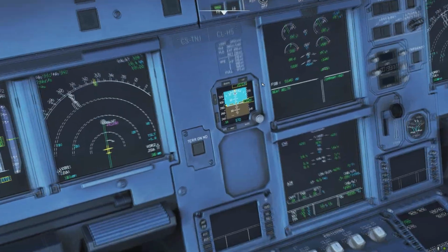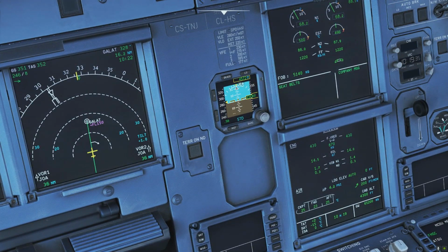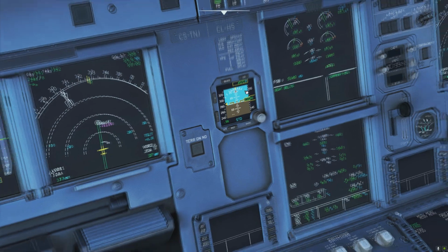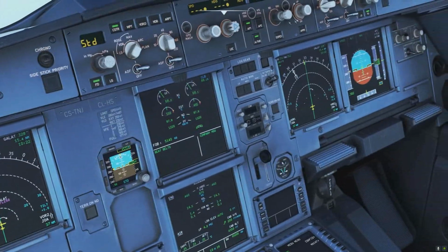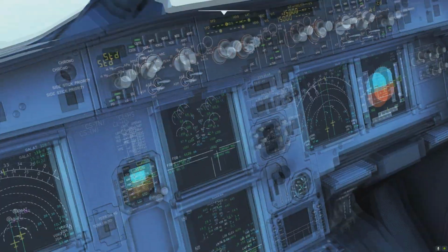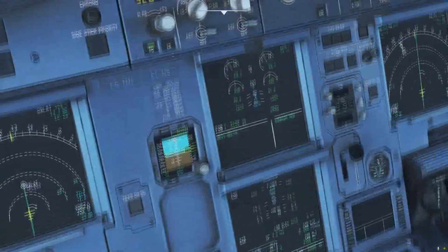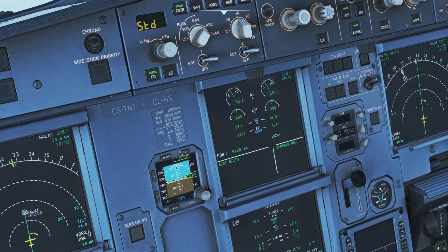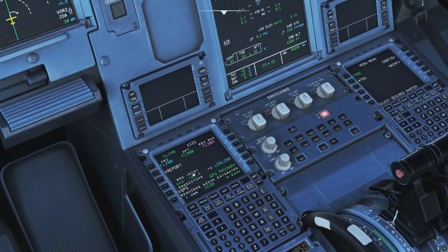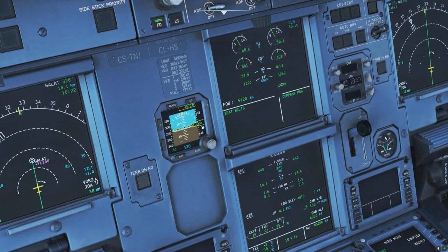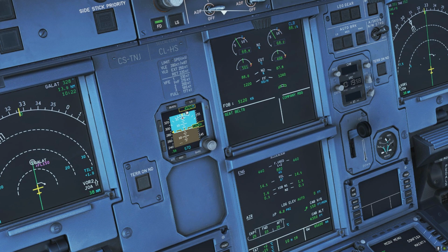On the Airbus you don't actually need to do this because you have this. We've actually discussed this already in one other video. The figure in meters works out pretty much the same as if you multiply this by 3. So this is the distance we have, and this is the distance we need. We have 80 miles, around about that. And to get down to the ground we need about, well, it says 45, but we add 10, so 55.